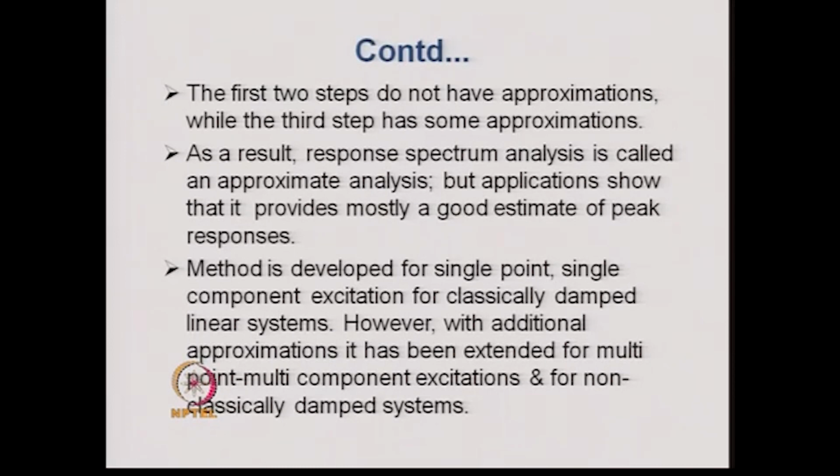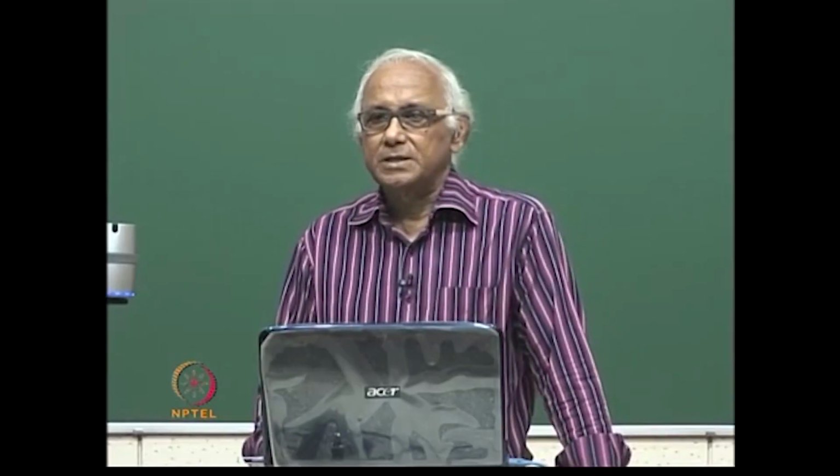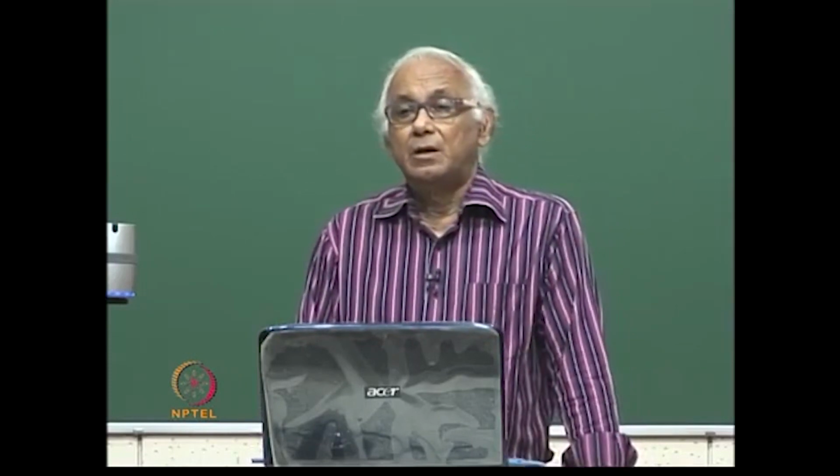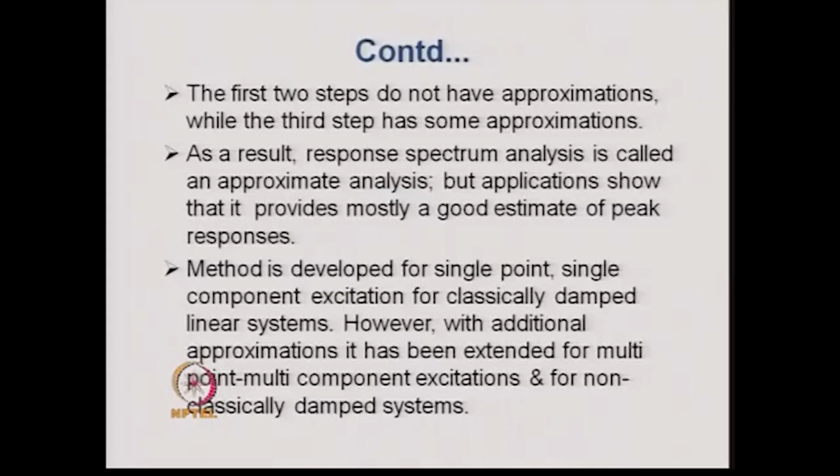Also, for multi-support excitations and multi-component excitations, the response spectrum method of analysis cannot be directly derived without making some kind of additional approximations, and we will look into this later.